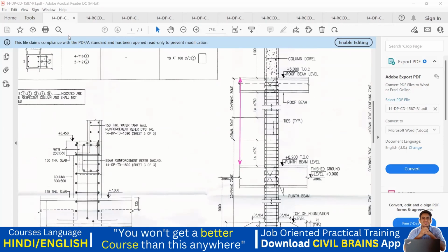And then you are going to get that confining zone. All these are your confining zone. From here to here, it has to be 750 confining. And from the bottom of your beam to this portion, it is 750. Okay. And the remaining is a normal zone. All these things, this is a roof beam. Exactly. See, they mentioned it as a roof beam, isn't it? That is what I told you. Roof beam, and this much portion will be a slab. You're getting my point? See, actually, this is slab. This much is a slab, because slab and beam will be cast monolithically, right? So that is why. And this much, the green one, is your beam. Got it?